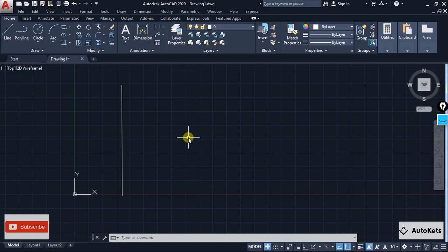To create a straight line, there is one tool available in AutoCAD, and you can say that this is a virtual scale provided to you, and that tool is known as Ortho mode. You will find this tool inside the status bar, symbolized as 90-degree. Whatever status bar tool is highlighted with blue color means that it is active, and if it is not highlighted, it means that it is inactive. Click on the 90-degree symbol over here. You can see that it will turn on the ortho mode.